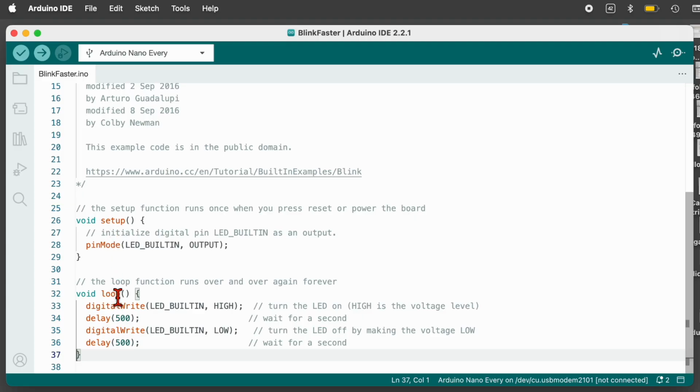Then, after that, the Arduino will continually call the loop function over and over and over until you turn the power off. And so in this particular case, we see one statement in the setup function. Statements run through a semicolon, and every statement ends with a semicolon. pinMode is another function. It's a built-in function that will define some particular pin on the Arduino as either an input or an output.